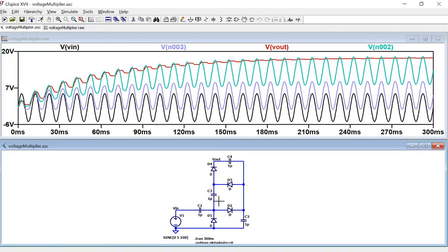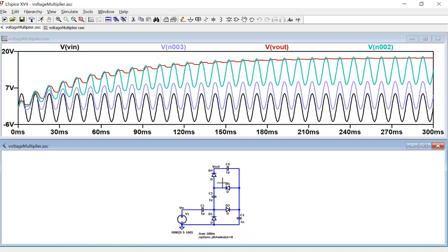And you can keep adding these stages to it, so you can get a pretty high DC voltage, 2,000 volts. You can just build everything on a breadboard, with all the caps and diodes being high voltage versions so they're not blown up. Just build a few stages, like 10, 12 stages, and you can get 2,000 volts. You can even see it: whenever you turn it on, after a while, if you place two metal pins close to each other, it's going to break through the air. You can see the sparks. Pretty high voltage, 2,000 volts. You can build it in lab. Be careful.